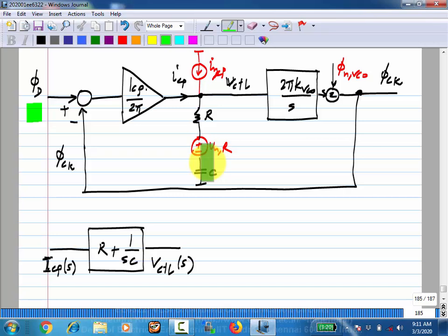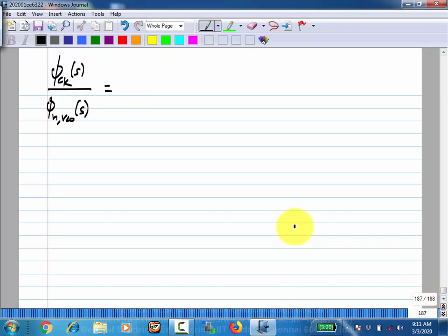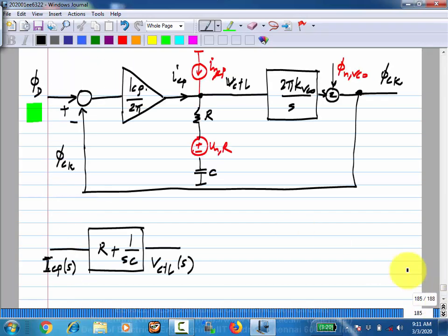Or maybe before doing all of this, okay, let's do one thing. So this is a negative feedback loop. First evaluate the loop gain. After that, we can do all of this. First evaluate the loop gain of this negative feedback loop. That will right away tell us constraints on some parameters. And after that, we can evaluate all the parameters. Oh, by the way, the phase detector gain should have another factor, which is the transmission.